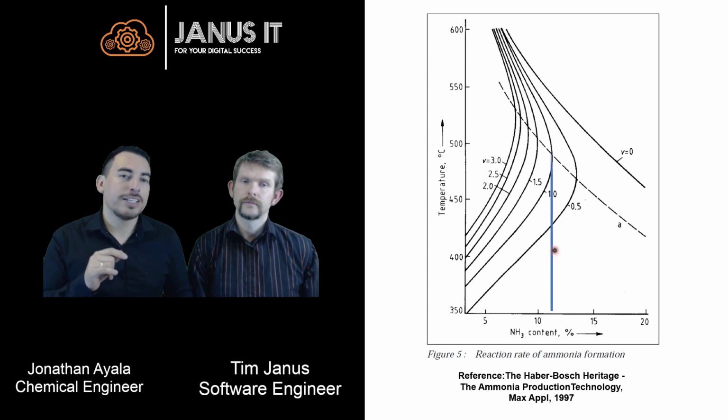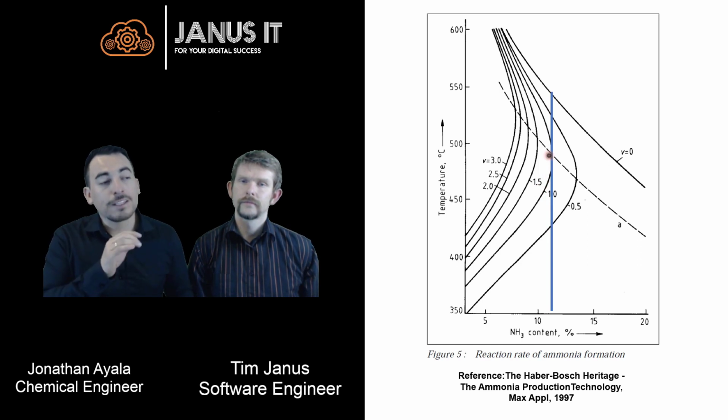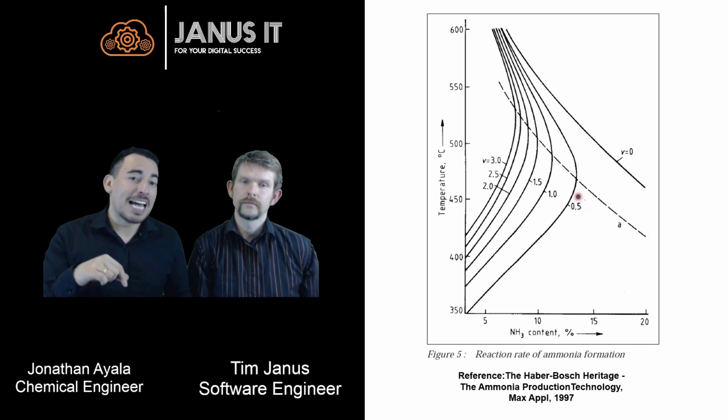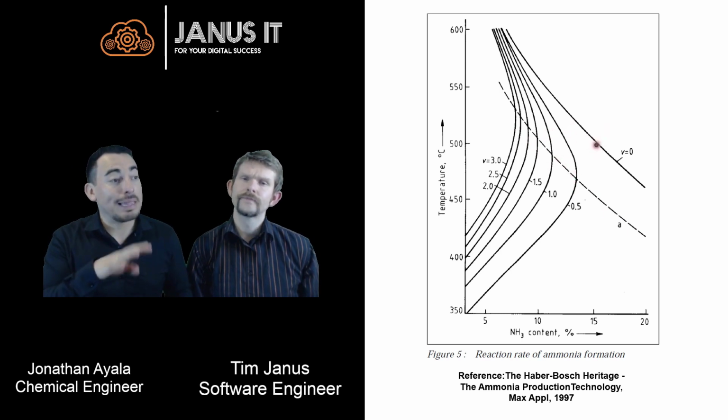As you can see, when the temperature increases, due to the nature of the reaction, it reaches a maximum point, and then if the temperature keeps increasing, it just goes down. Joining these maximum points will give us the temperature for the maximum rate for each ammonia concentration, and this line runs parallel to the equilibrium line and around 30 to 50 Celsius below.